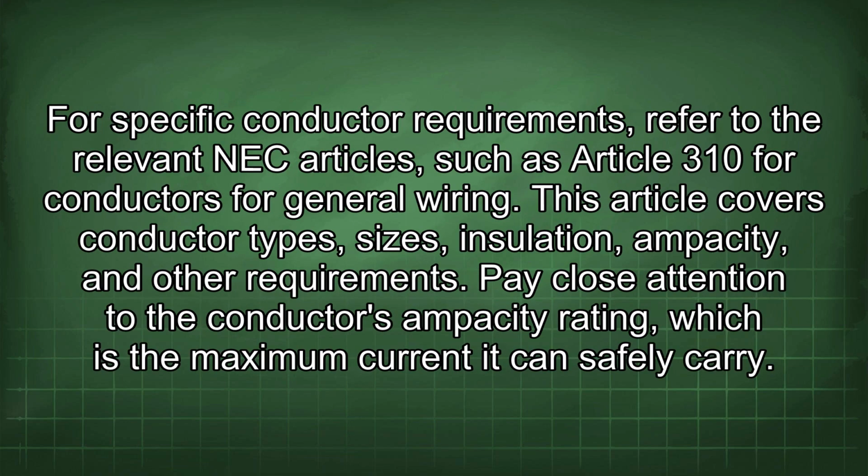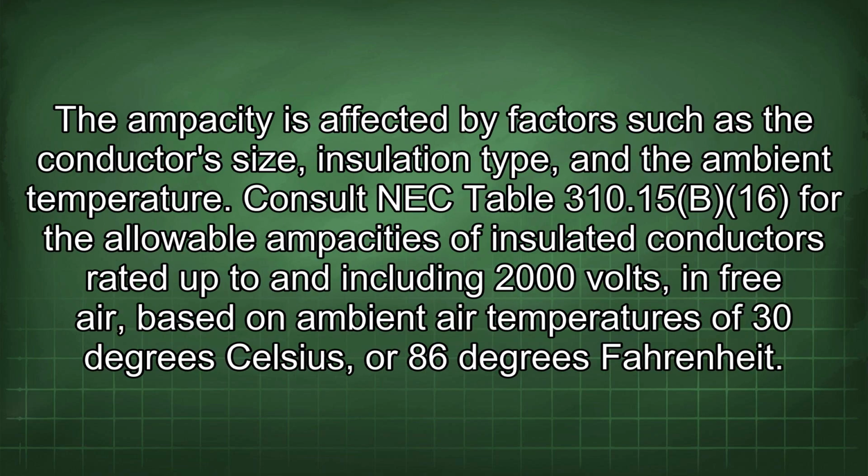For specific conductor requirements, refer to the relevant NEC articles, such as Article 310 for conductors for general wiring. This article covers conductor types, sizes, insulation, ampacity, and other requirements. Pay close attention to the conductor's ampacity rating, which is the maximum current it can safely carry. The ampacity is affected by factors such as the conductor's size, insulation type, and the ambient temperature.